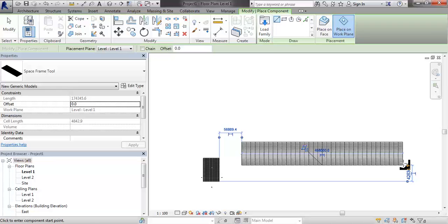Okay. The things we can add to this, right, is now I have this tool. You can think of this as space planning or anything. I can load in this idea of being able to load in multiple families. Let's say I was doing a line of offices that were all 100 square feet, or I didn't know what I want them to be. I could load in furniture into the system like this methodology, and I can begin drawing out lines of offices, right, at any length, width, and height that I want with all the furniture already in it.